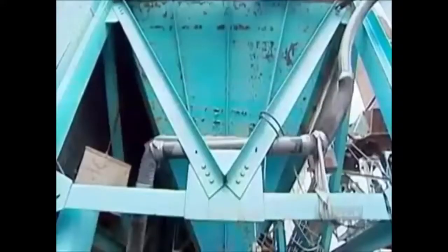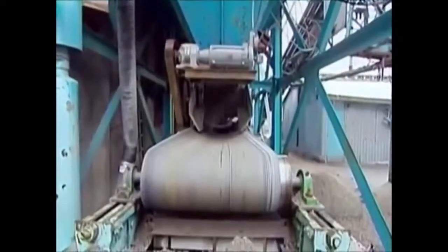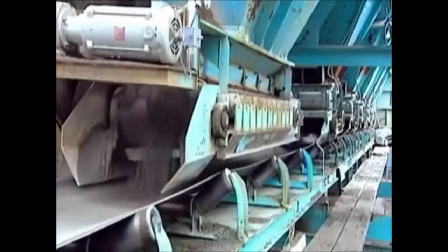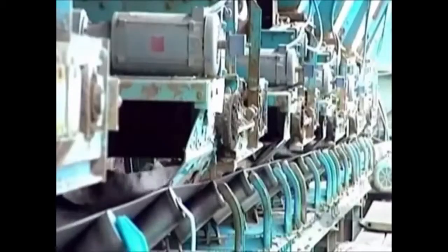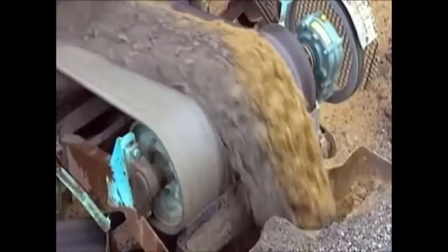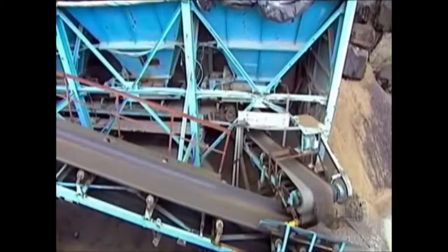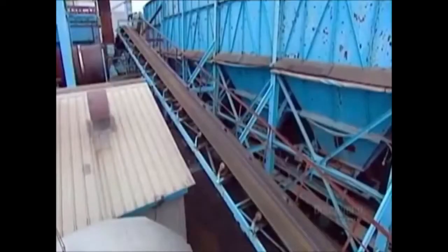Stones, along with sand and stone dust as fillers, usually make up about 95% of the mix. The remainder, added later, will be liquid asphalt cement. Each bin releases a specific amount of material onto a conveyor belt running under it. The belts lead to a main collecting belt that dumps the ingredients combined onto yet another belt that leads to a dryer.